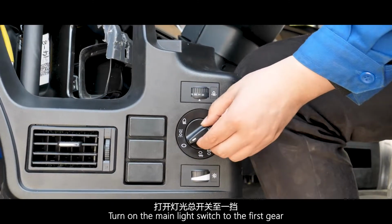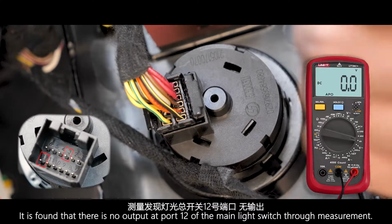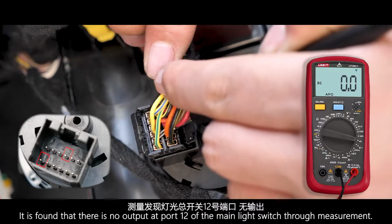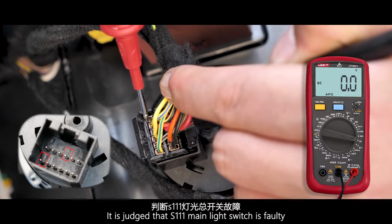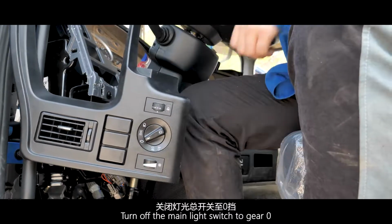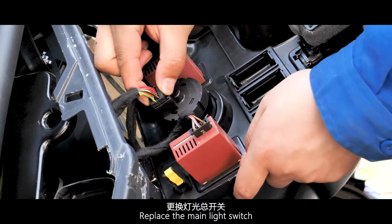Turn on the main light switch to the first gear. It is found through measurement that there is no output at port 12 of the main light switch. It is judged that the S111 main light switch is faulty. Turn off the main light switch to gear 0. Replace the main light switch.